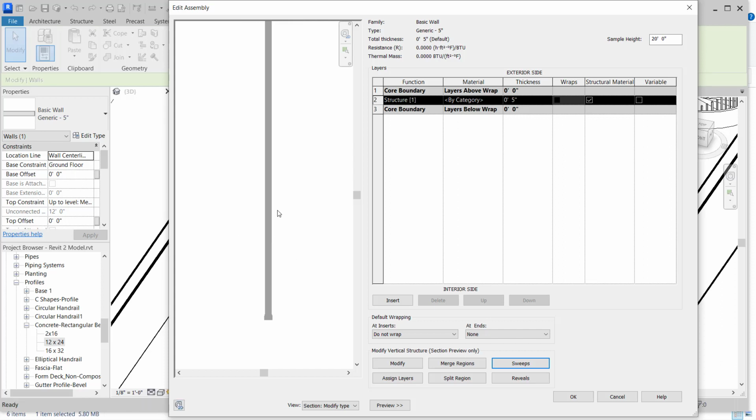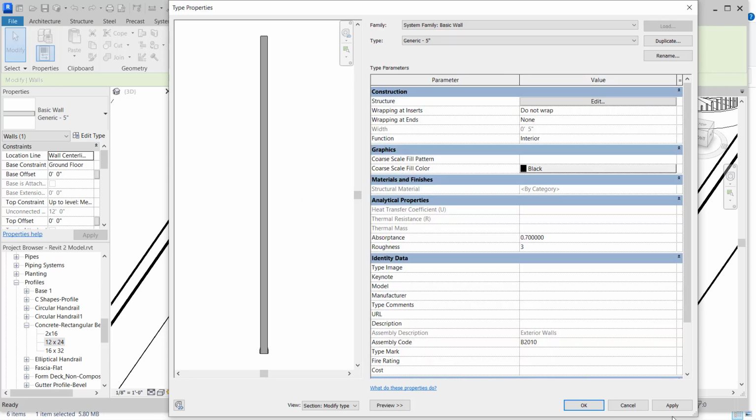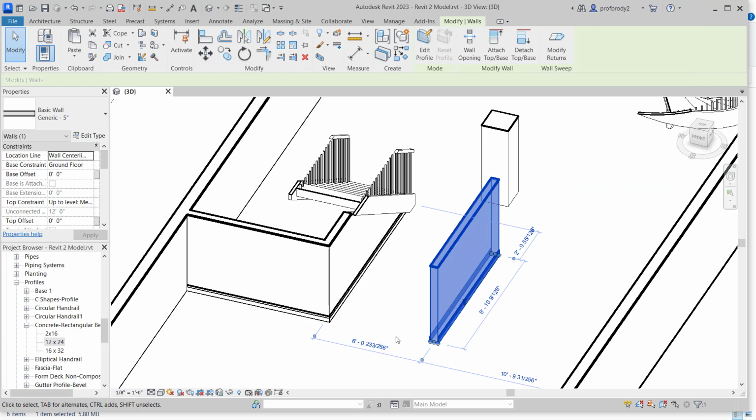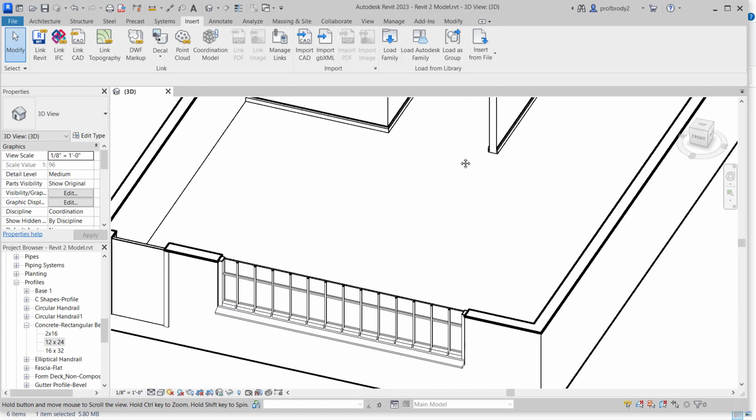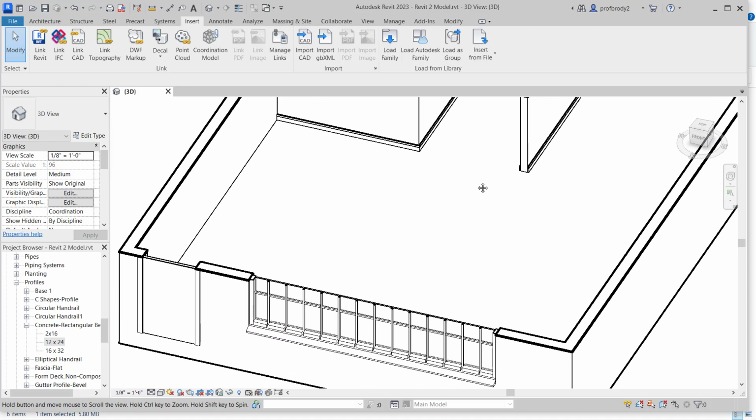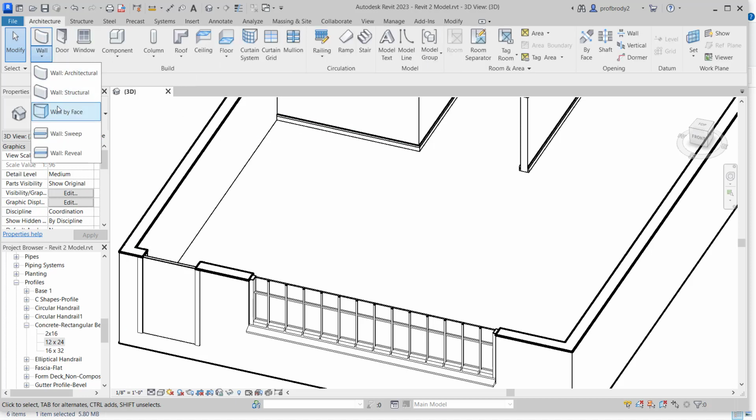You can do the same thing with crown moldings and even things like wainscoting; you can add them in this way. So I'll just click OK through the menus. Again, you have to kind of cycle through all the menus. But what you should see is all of your interior walls have a little base on them. Could we do this with the exterior wall? Absolutely, we could. The problem is our exterior wall actually goes into the ground. So if you were to add these bases onto the wall, it would be underground. That's not so good. So you can still go ahead and create a sweep that uses this profile and add it to the interior walls.